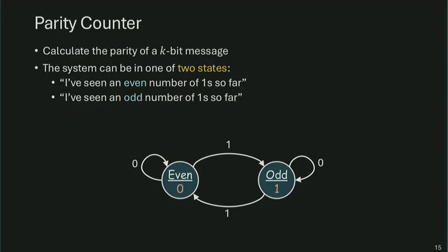And you see, that's actually the same state diagram as the T flip-flop except that now we are also annotating the state with a number, and that is the output value. So suppose I wanted to produce a 1 when an odd number of ones has occurred. So whenever I'm at the odd state, the output will be a 1 to tell me that so far I have seen an odd number of ones. When I'm at the even state, output will be 0. Right. So really, in terms of a circuit implementation, you just use a single T flip-flop and then connect the state to the output port.